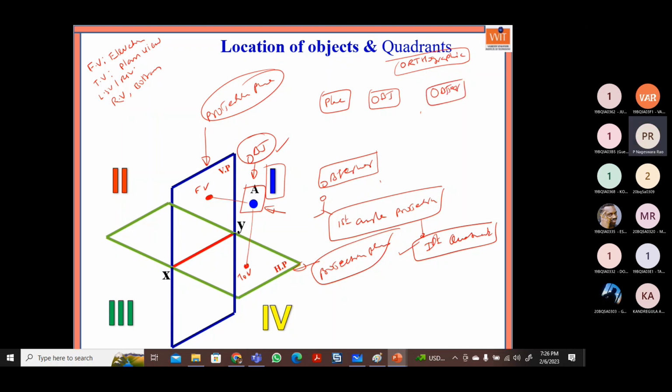Now I can say that in first angle projection, if the object is in between the plane of projection and observer, then such type of projection is called first angle projection. So if the object is in any view, not only in the front view, we can say side view, top view also, this is applicable.